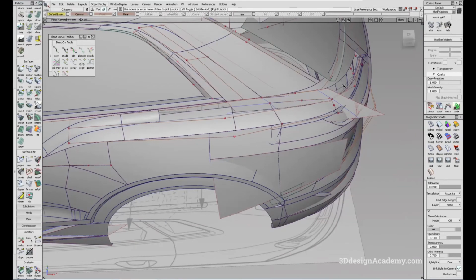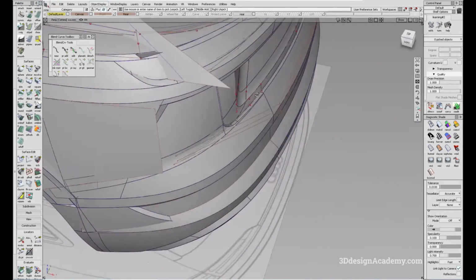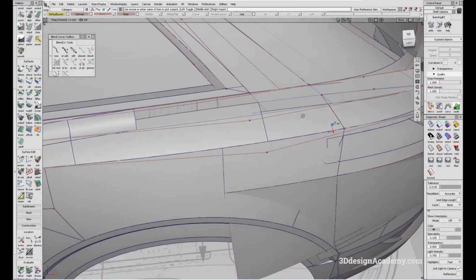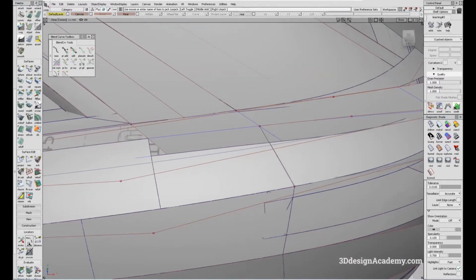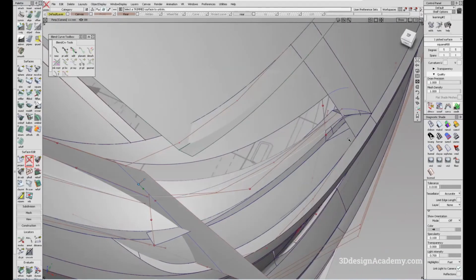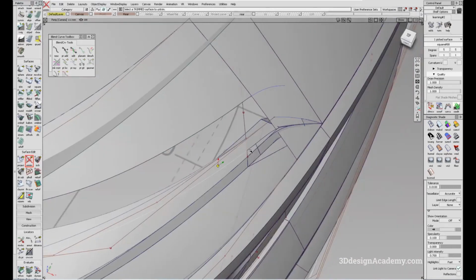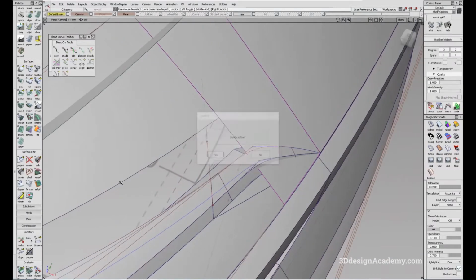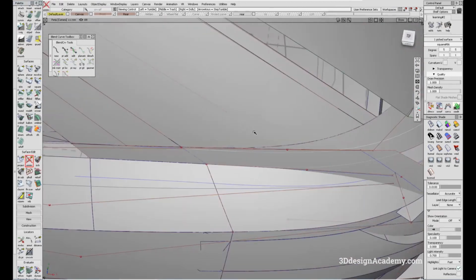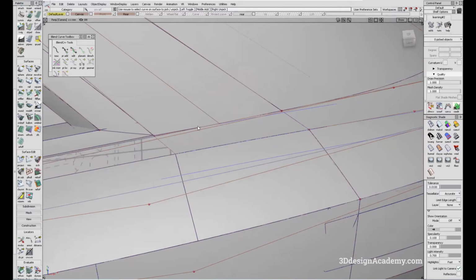Now, the surfaces over here, it looks like it's missing surfaces, but I think I might have just deleted the fillet. So what I'm going to do is I'm just going to untrim all the pieces over here and over here. I'm going to try to run the fillet again. Okay, so I'm going to untrim here like that. And I'm going to, okay, this one also untrim.